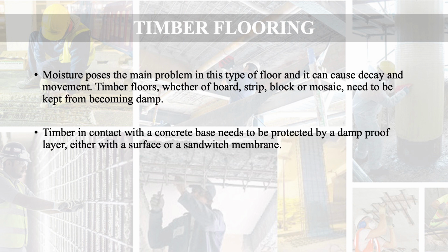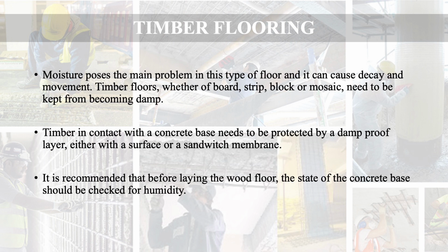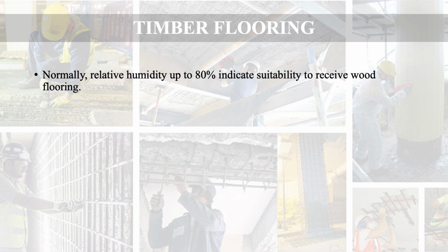Timber in contact with a concrete base needs to be protected by a damp-proof layer, either with a surface or a sandwich membrane. It is recommended that before laying the wood floor, the state of the concrete base should be checked for humidity. Means that humidity should be within the limits. Normally, relative humidity up to 80% indicates suitability to receive wood flooring.